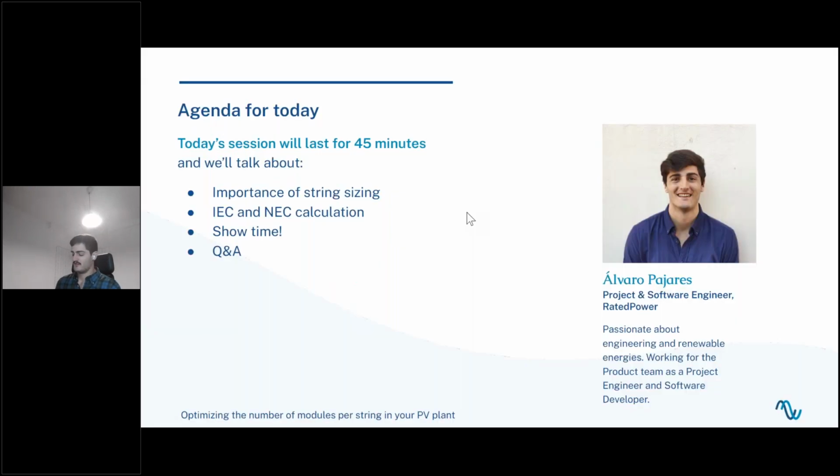I hope you enjoy this session, and here we will speak about these 4 main points. The agenda: first, we will start with the importance of the string sizing. I will try to explain the most important aspects with regards to this string sizing, where the amount of modules that we connect to build one string affects the PV plant and its main aspects.